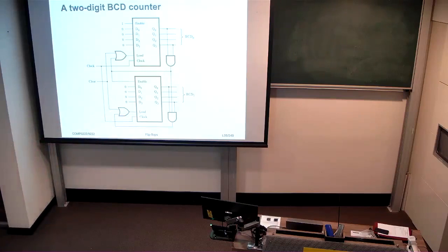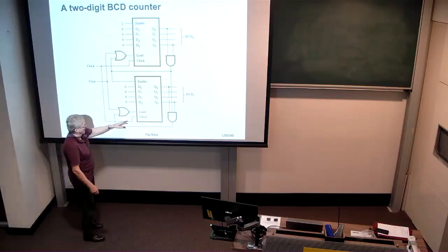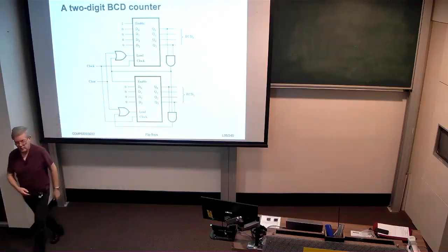Okay? We can also clear the counter to 0 by asserting this clear signal here. So it's a really neat little design for a stopwatch, let's say, which is counting hundredths of seconds, assuming that the clock here were set to be 100 hertz.